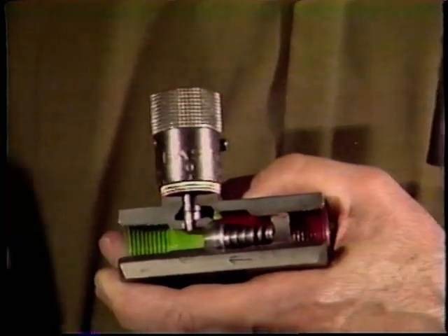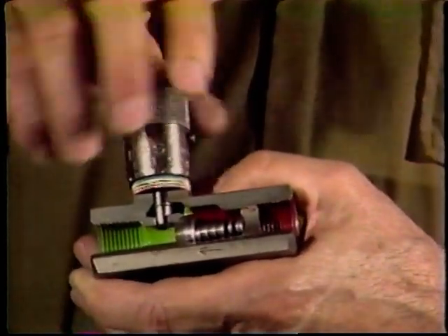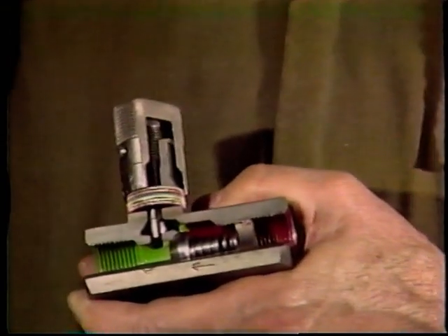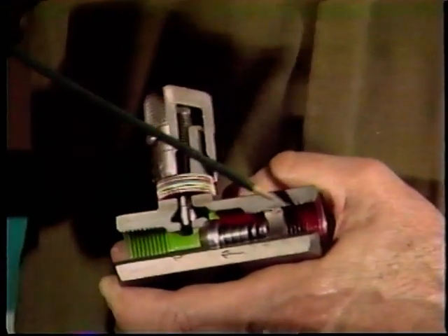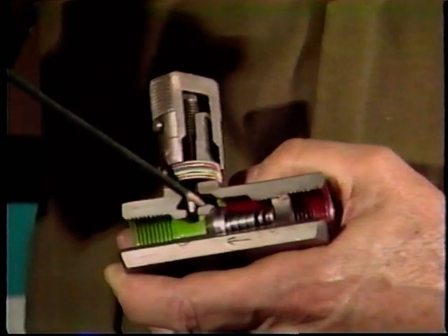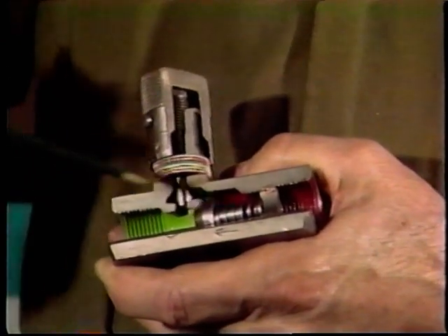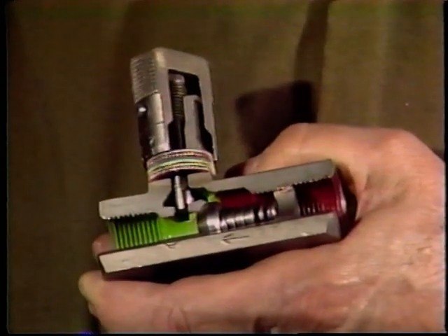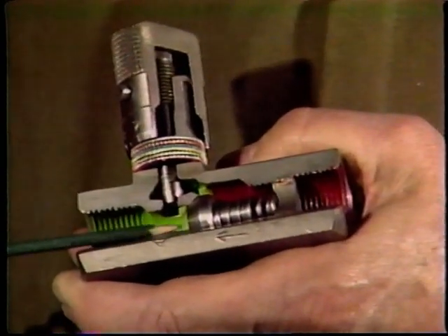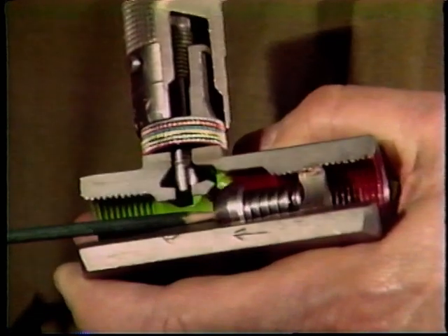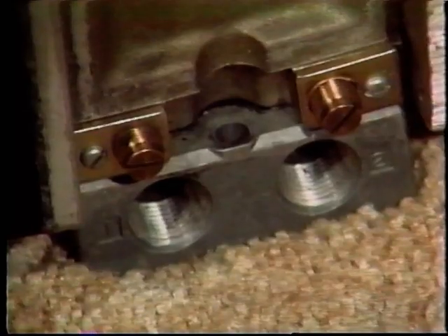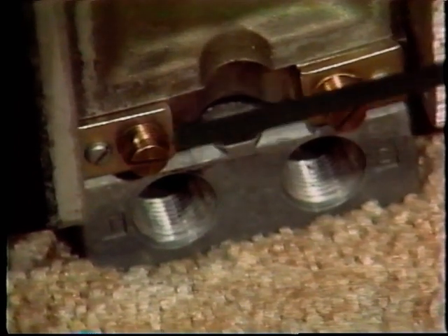Before we go further, we should mention one other important point about using adjustable flow control valves. That is, in most system designs, flow control valves are used to regulate flow in only one direction. So the valve construction often has an internal bypass check valve which offers little resistance to airflow in the reverse or free flow direction. Here is a typical needle valve package.